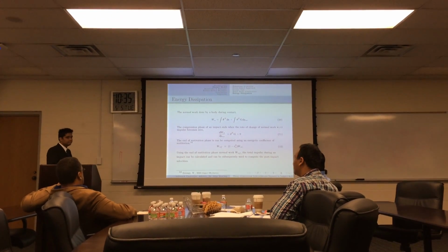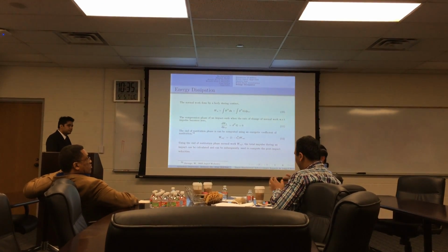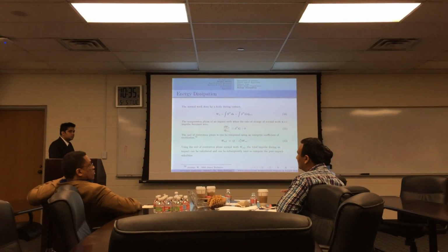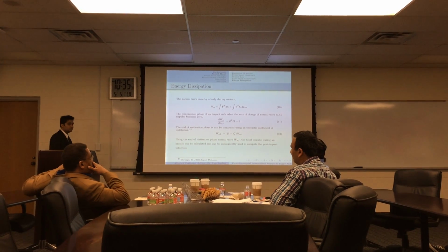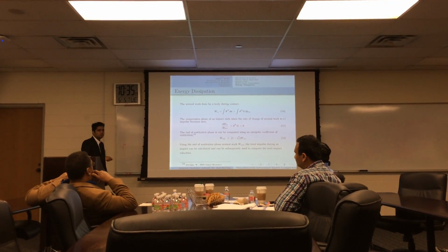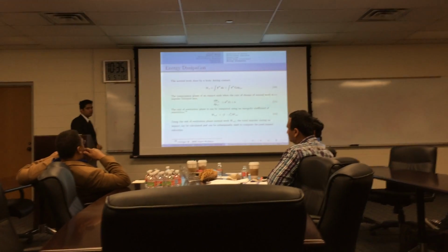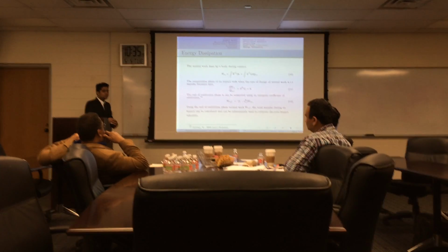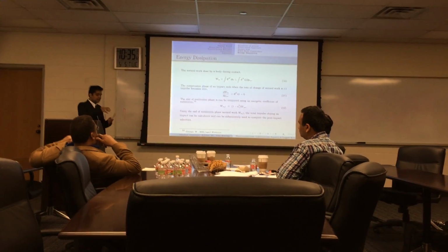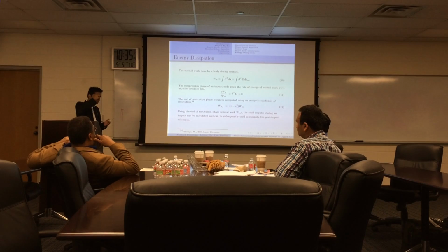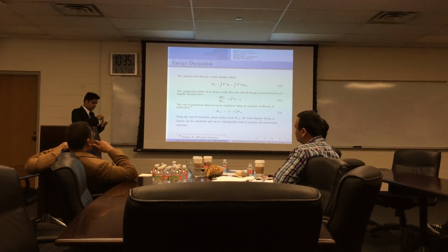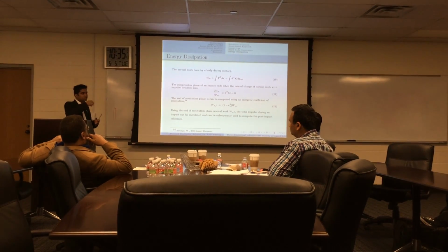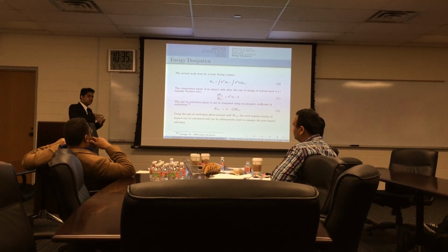But the initial velocity that we're talking about is kind of the whole global velocity of the robot, right? Going, let's say, parallel to the surface. No, it is the velocity of the contact points. That is what is important over here, because that determines what our energy loss would be. Because from a deformable point of view, it's really that parts of the body are deforming, and because of the elasticity, that's where the energy is lost.